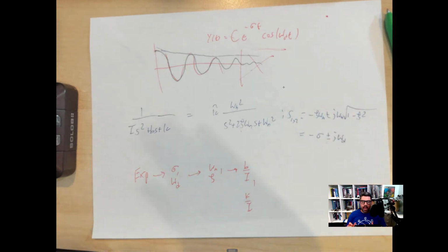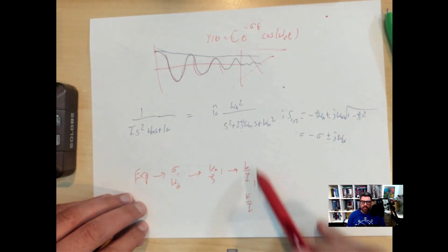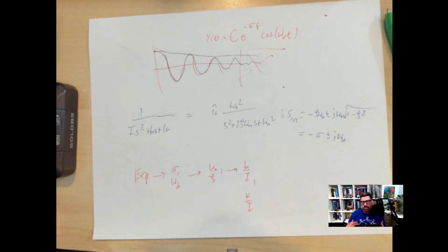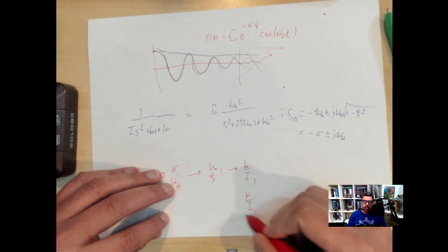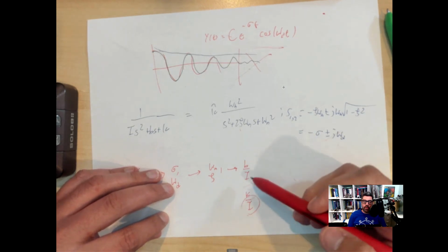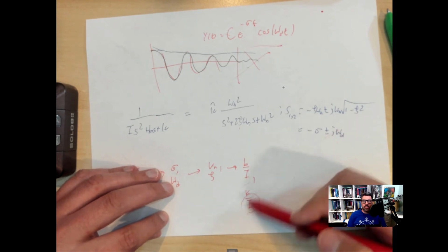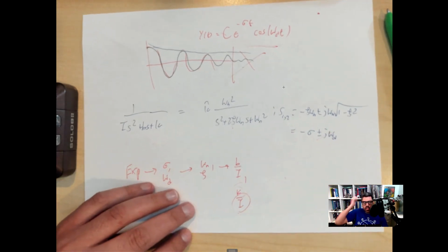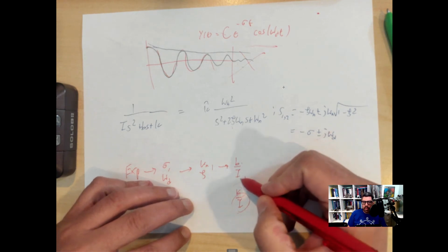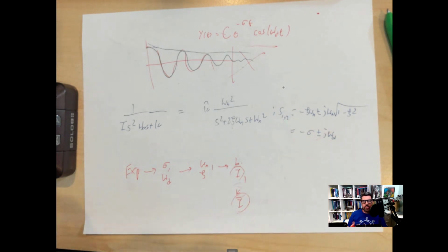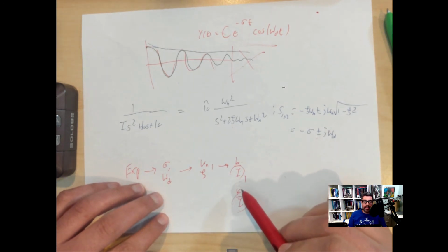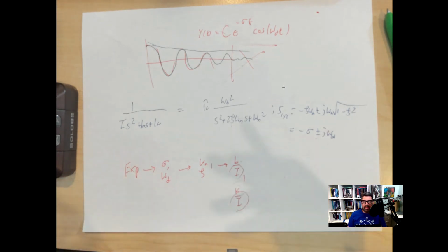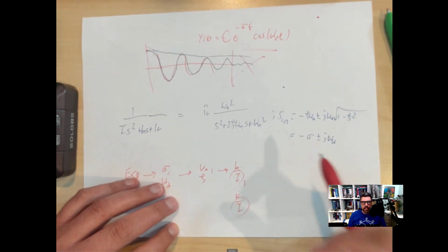So here's where you have a little problem. Here's two equations, but I have three unknowns. So in this specific experiment, you actually need to use one of your theoretical values to get the other two values. Now, just as a little foreshadowing, there are mechanics of materials, solids, tools that you can use to approximate I theoretically and K theoretically. But B, the damping, the energy loss in that system, that's so hard to find.